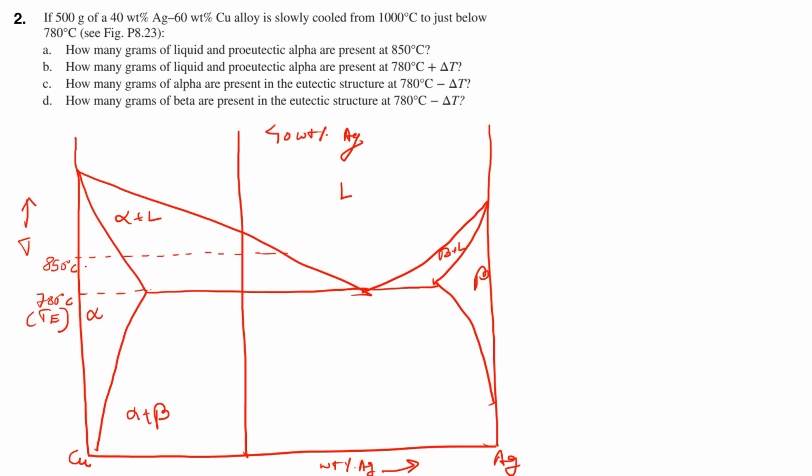So for working this out, we will always be given the actual phase diagram, wherein we can get the compositions from the intersection points, right? So at 850 degrees centigrade for question A, the weight percent of liquid can be given by this arm, which is 40 minus this was 7.9.